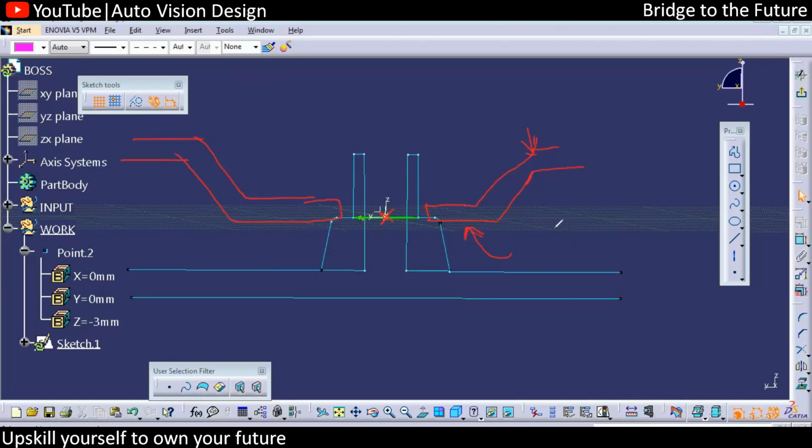Okay, so maximum to minimum we can check. From this to this we need to have somewhere close to 3, 5 or 7. Okay, so 3, 5 or 7. Minimum 3 we can keep like a rib height. With respect to that, again to remove other things, minimum something like 2 mm is also sufficient, 1 mm is also sufficient, but that will not add value, because again the part to part clearance is also important.